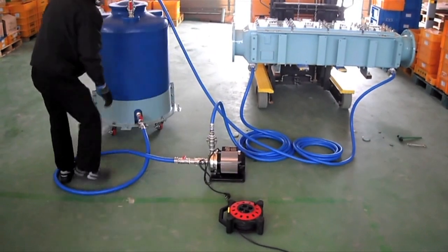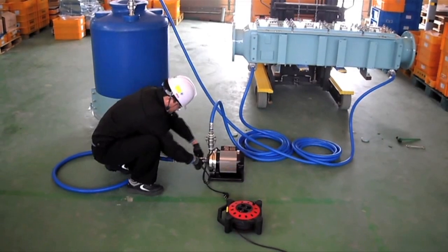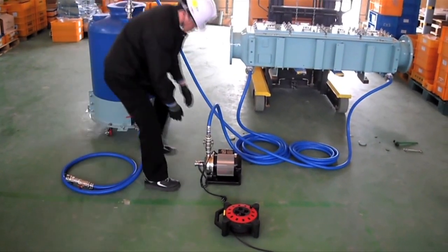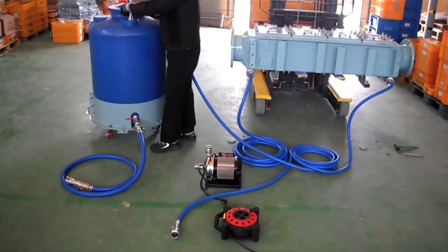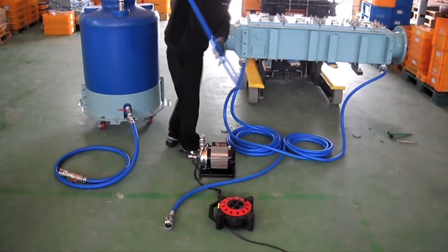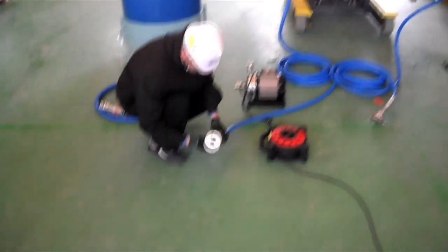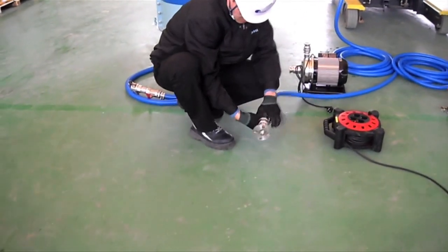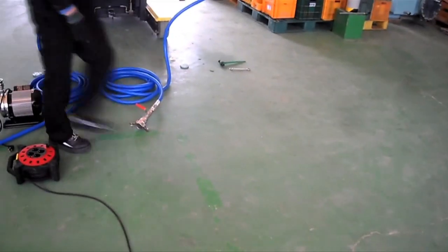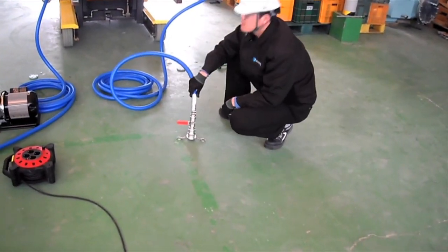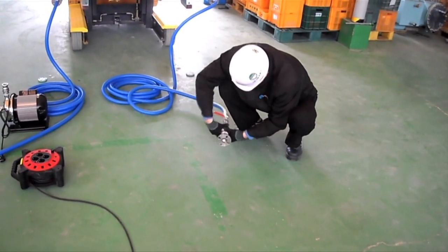1. Close valve V1 of tank outlet. 2. Connect the freshwater cooling service line of ship to tank T2 using pipe EC3. 3. Drain seawater from chamber through drain D1, D2 of ECU. 4. Inject cleaning agent with fresh water. Please refer to Table 1 below for the appropriate amount of cleaning agent and fresh water. 5. Disconnect the fresh water pipe from tank T2.